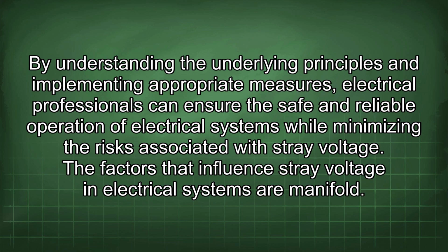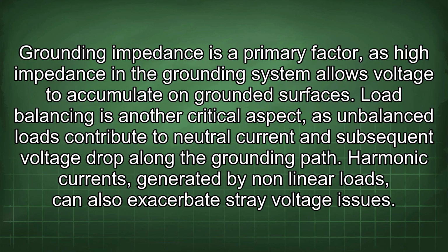The factors that influence stray voltage in electrical systems are manifold. Grounding impedance is a primary factor, as high impedance in the grounding system allows voltage to accumulate on grounded surfaces. Load balancing is another critical aspect, as unbalanced loads contribute to neutral current and subsequent voltage drop along the grounding path. Harmonic currents, generated by nonlinear loads, can also exacerbate stray voltage issues.